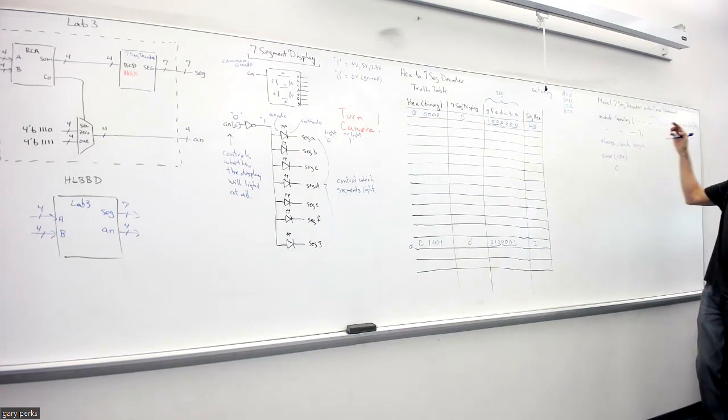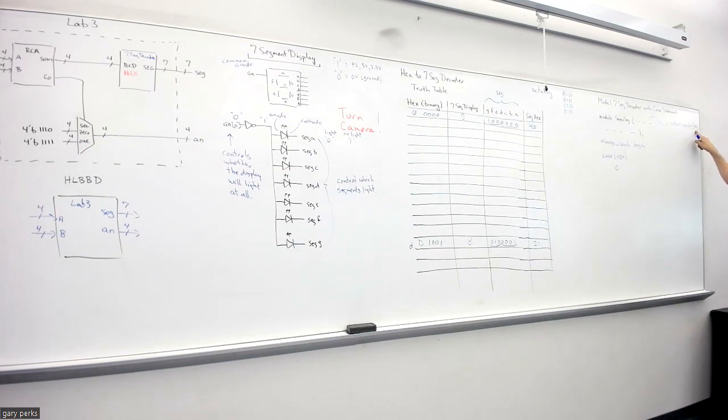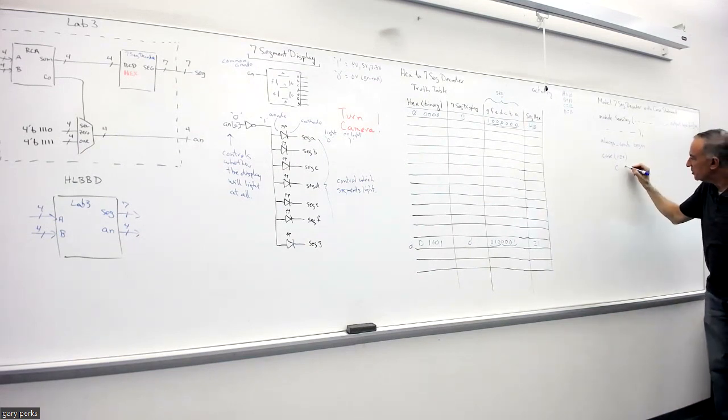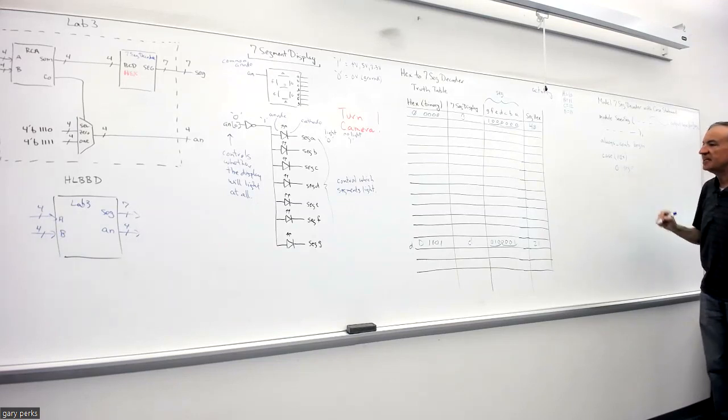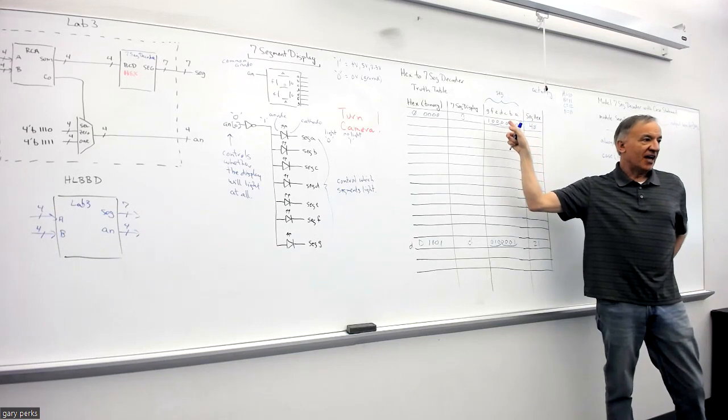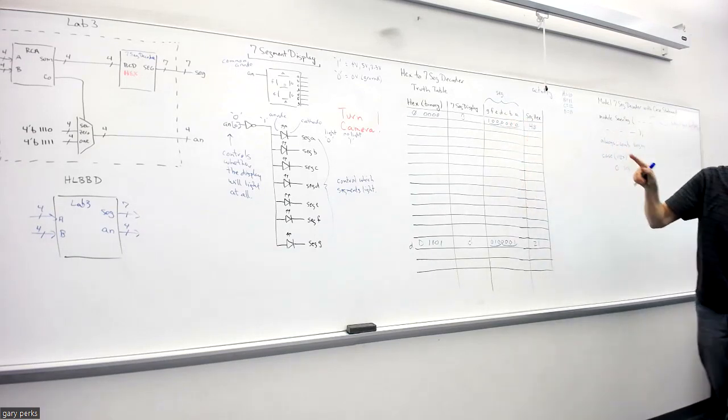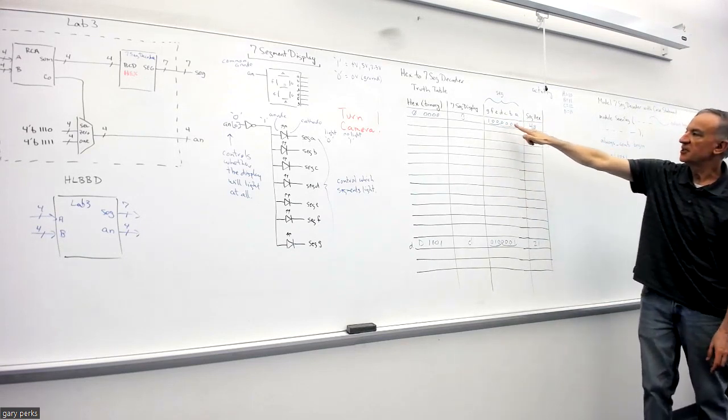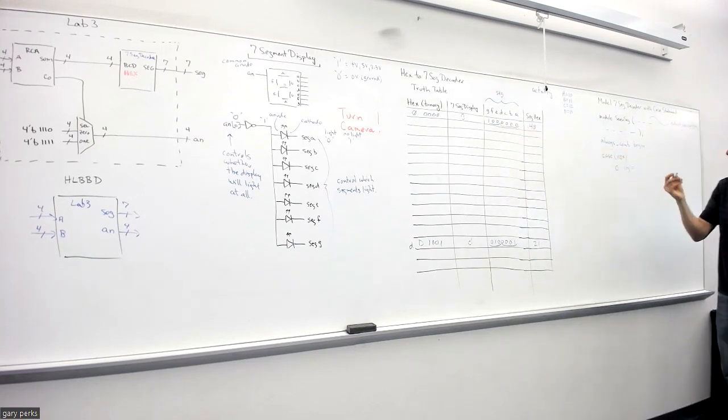And then let's say, well, we called our segment output seg. So then we would just put our output seg and then set it equal to the bit values, okay, the cathode bit values. So for 0, we want what you see here, this 40 hex. So you would write 7, right, because there's 7 bits, tick mark B for binary, and then you would just put those bits. So it'd be 1, 0, 0, 0, 0, 0, 0. Is that 7? 7, and then I think you have to end it with a semicolon.